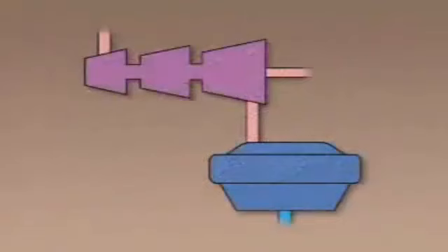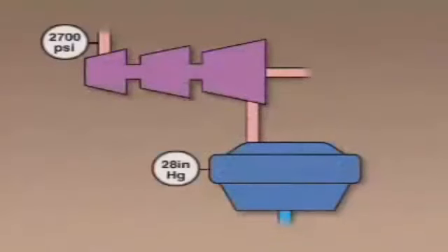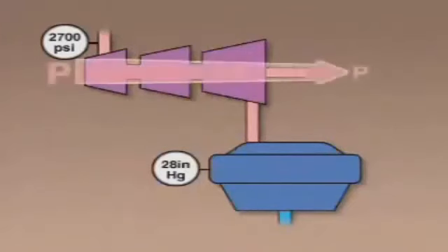Another way the condensing process improves efficiency has to do with the fact that most main condensers operate at a vacuum, that is, at pressure below atmospheric pressure. Since steam enters the turbine at high pressure, the vacuum inside the condenser means there is a significant pressure drop across the turbine stages. And the greater the pressure drop across the turbine, the greater the useful output of the turbine.